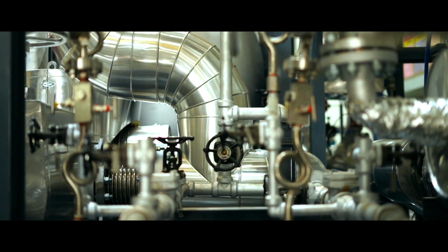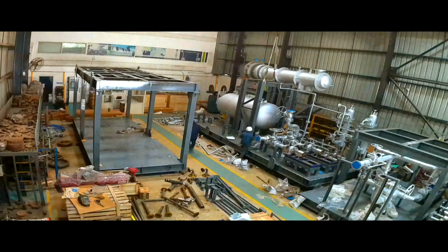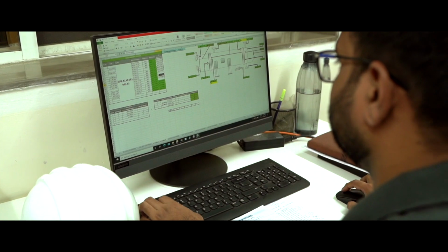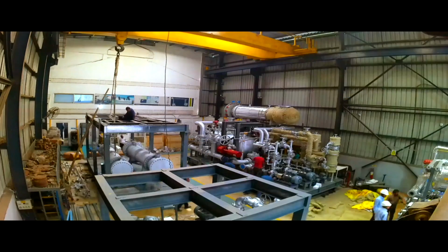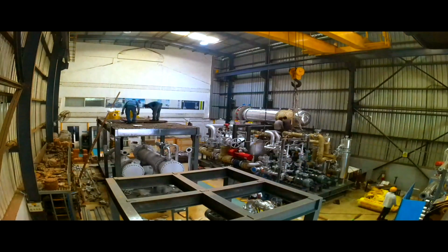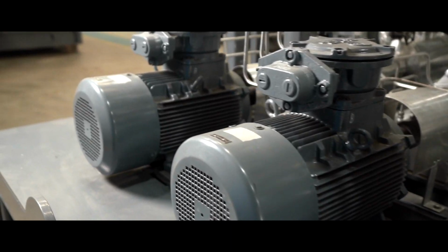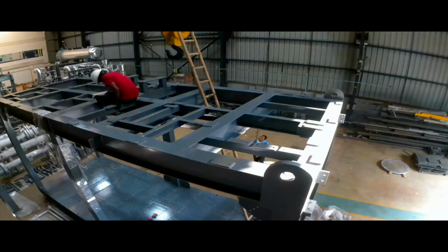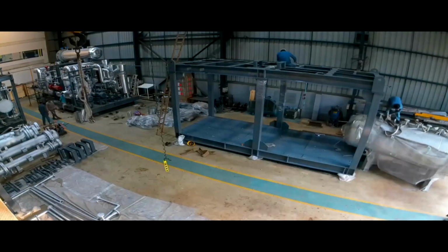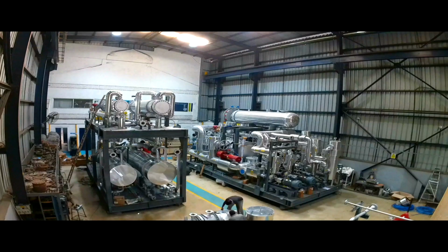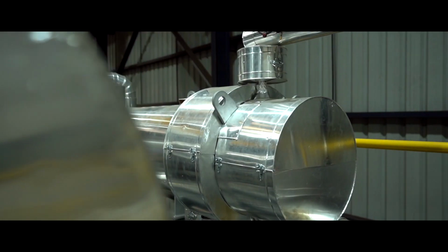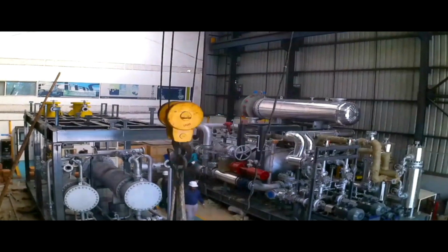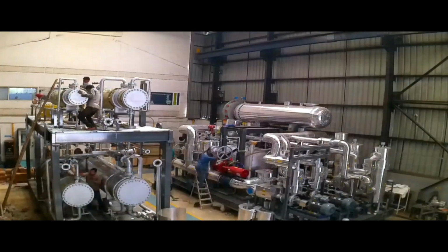The equipment, piping spools, and skid base frames are manufactured as per fabrication drawings, painted and assembled, along with bought-out components such as valves, pumps, and instruments. Cabling and tubing within the confines of the individual skids is challenging as well as time-consuming. Insulation of the skid equipment and piping is also quite difficult given the space constraints.